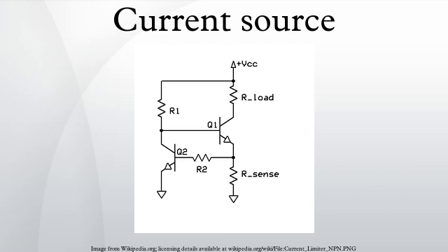or, since VBE is typically 0.65 V for a silicon device, IR2 is also the emitter current and is assumed to be the same as the collector or required load current, provided hFE is sufficiently large. Resistor R1 is calculated as given, where K equals 1.2 to 2, and hFE min is the lowest acceptable current gain for the particular transistor type being used.